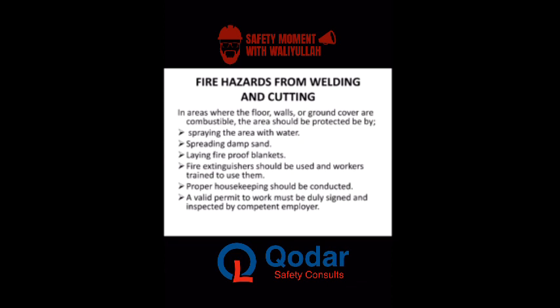There are some construction jobs that will require you doing some welding or cutting in a place that has combustible materials. If we find ourselves in that kind of situation, what do we need to do? Well, it is advisable that we spray the affected area with water where that work is to be done. We want to spread damping sand. We want to lay fireproof blankets. We want to also ensure that the right fire extinguishers are in place. Proper housekeeping and a valid permit to work should be in place for this kind of job.